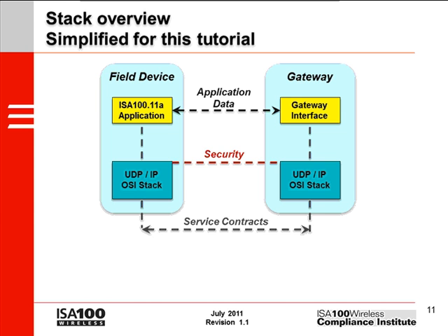The service contract approach preserves layer independence and makes it much easier to add new radios to ISA100 in the future. Service contracts also make life much simpler for the application developer today. The stack handles TDMA, CSMA, and similar considerations completely transparently.